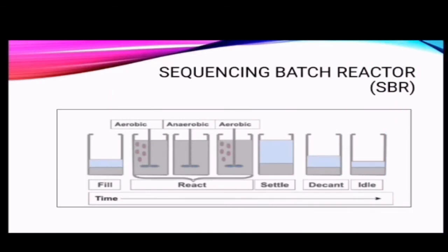The first method that I want to present is the SBR, which stands for sequencing batch reactor. SBR can remove the unwanted elements and then discharge the water to a suitable place after being treated. The processes of equalization, aeration and clarification can all be achieved using a single batch reactor, and the performance of the system can be optimized by implementing 2 or more batch reactors. The SBR system promises to reduce operating costs and plant space.